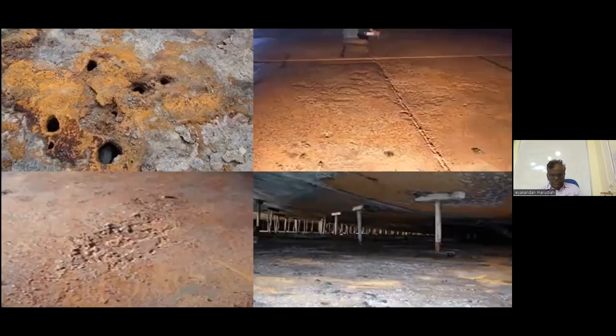Tank corrosion sometimes increases when a layer of water containing soluble salts and chloride settles to the bottom. These compounds are highly corrosive in themselves, and they can generate a strong electrolyte that further promotes corrosion from within. There can be a problem with external tank corrosion as well. The bottoms of above-ground storage tanks are susceptible to corrosion, especially if the tanks are close to salt water or subject to stray electrical currents in the soil.